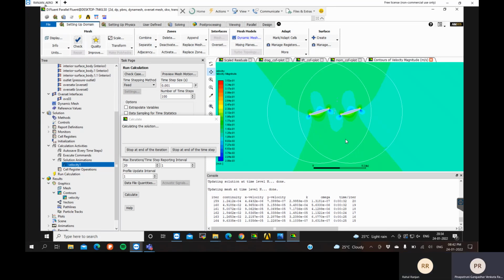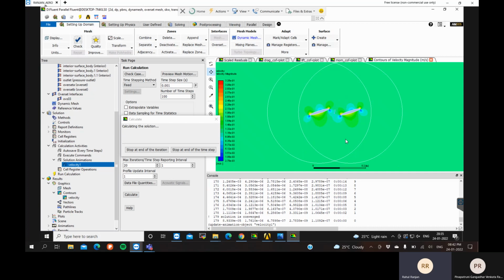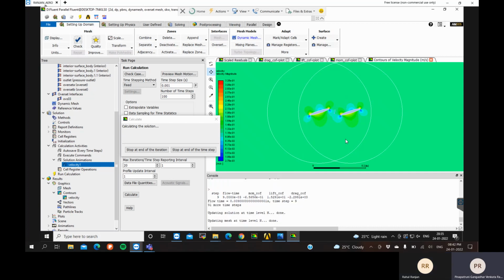It is not mandatory to use a circular one. That's your wish. I think even an ellipse is okay, but you can try it. If the ellipse is giving a good orthogonality mesh compared to the circular, then we can work with the ellipse only. Unless we try that, we cannot comment on it. I need to check the orthogonality, which will generally be around 0.5. A structured mesh will automatically give you a good orthogonality. If it is still problematic, then we have many things to deal with.